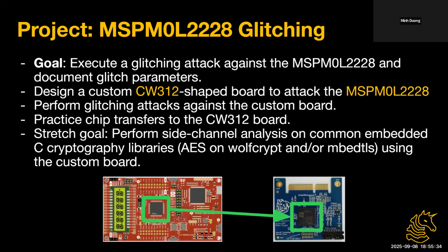That's why it's important, and we're going to teach you how to write mitigations against common types of attacks. As Jake mentioned, one thing you can do is double, triple, quadruple checks to make sure that code executed correctly, if you have something super critical that you're executing. Another thing you can do is randomly decide when to execute that instruction, because a lot of voltage glitching relies on precisely timing where you're going to do the glitch. If you add random delays, it's a lot harder to do that. But there are ways to get around this, and it's kind of a game of cat and mouse.